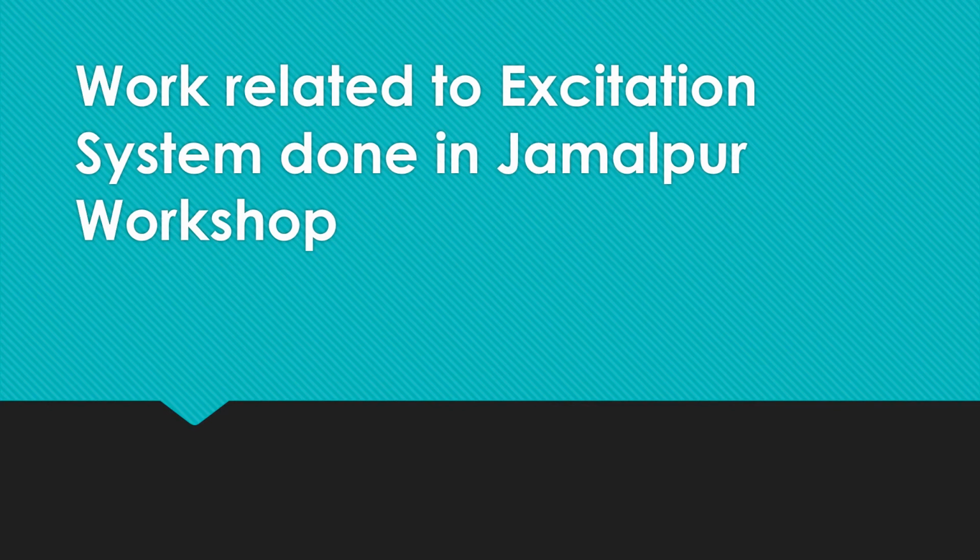Now the work related to the excitation system done in Jamalpur workshop. In Jamalpur workshop, the work is done mainly on E-type excitation and the excitation panel, which has 7 cards, which are inspected and overhauled. The cards are electronic, having subparts such as diodes, transformers, small capacitors, resistors, etc. The usual life is 12 to 15 years and there are no such must-change items. Repairs are carried out in case defective cards arrive. But items like capacitors cannot be repaired in Jamalpur workshop, hence they are replaced.